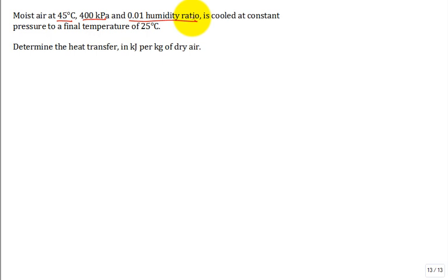It fluctuates as the temperature and the humidity changes. So if you're over in Houston, you're going to have more challenges with water in your compressed air system. If you're in El Paso, you have less challenges. True? That's right. A lot of times in these compressed air systems, they'll have dryers and filters before that air gets to their tool. And if they don't, some tools can accommodate water vapor, but some tools can't. And if you're in a paint spray shop and you use air, you don't want any water going into your paint gun, right? You want it dry.